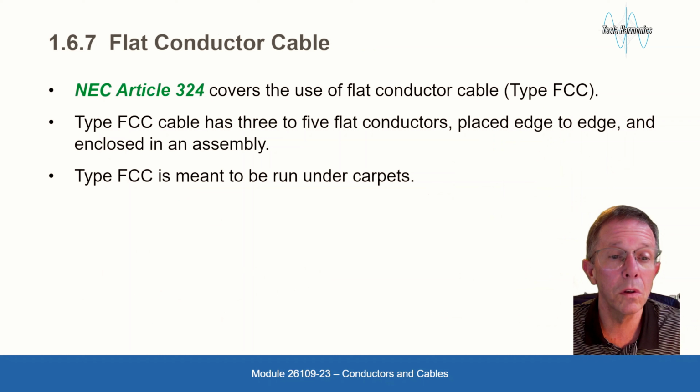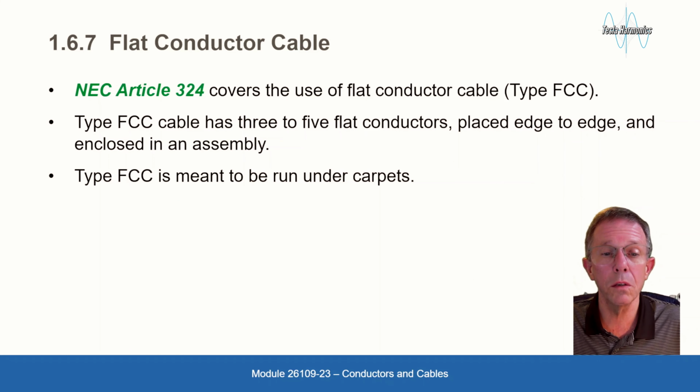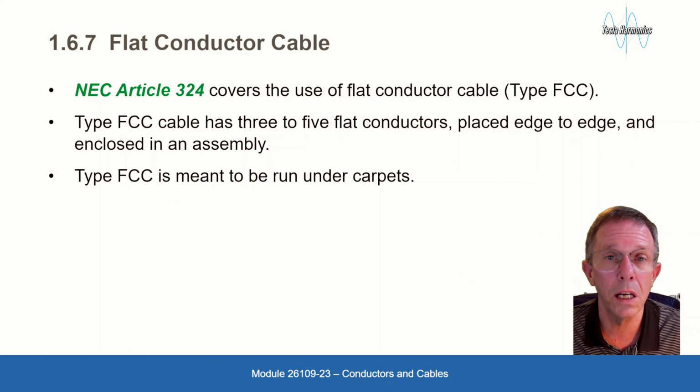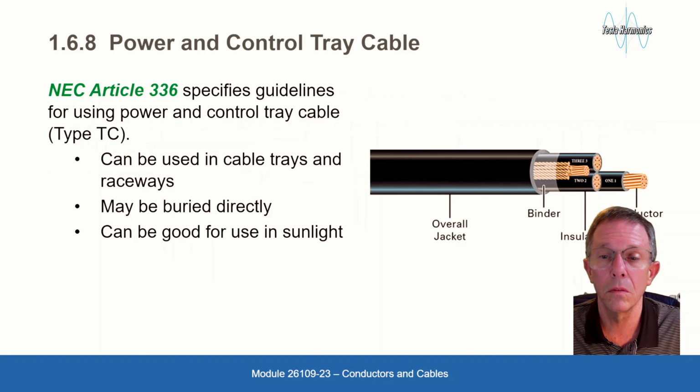Flat conductor cable. NEC Article 324 covers the use of flat conductor cable, or type FCC. Type FCC cable has 3 to 5 flat conductors placed edge to edge and enclosed in an assembly. Type FCC is meant to be run under carpets.